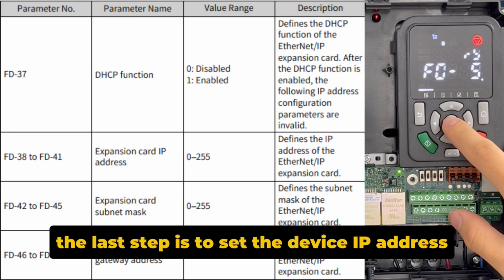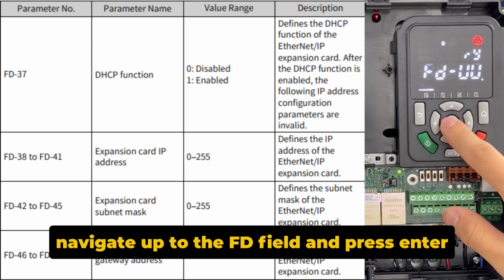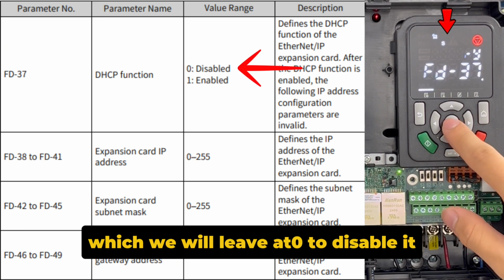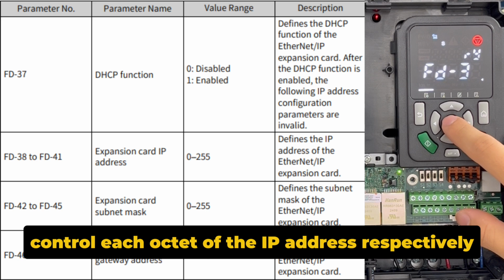The last step is to set the device IP address. For this part, we will press the back button, navigate up to the FD field, and press Enter. The first field, FD37, controls the DHCP function, which we will leave at 0 to disable it. The fields FD38 to FD41 control each octet of the IP address respectively.